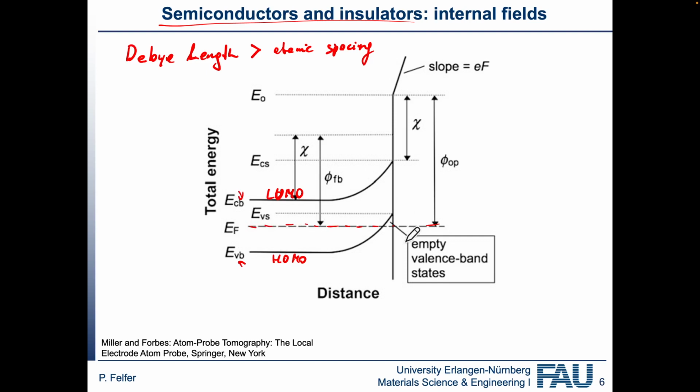And what we now do is essentially we bend the Fermi level because we are moving a field in. Through the field, we are bending what the energy of the Fermi level is. Because remember, the energy contribution is elementary charge times field times some distance, very simply. And this is the contribution we see here, overlaid with the charge density that's in here.